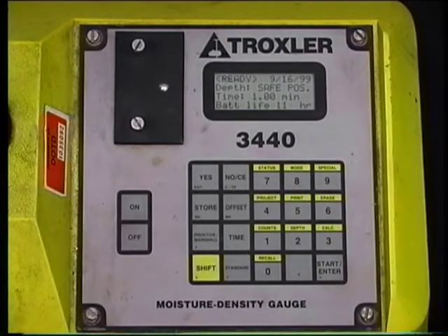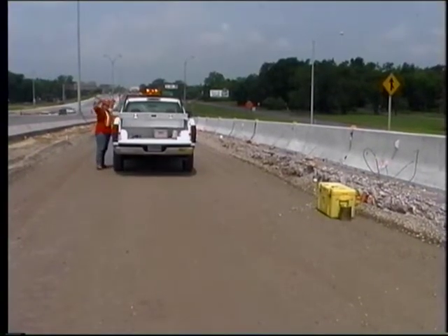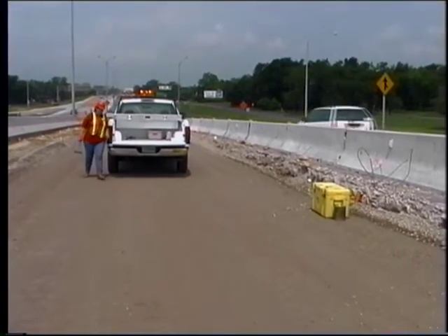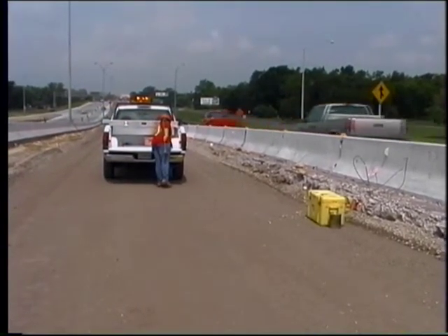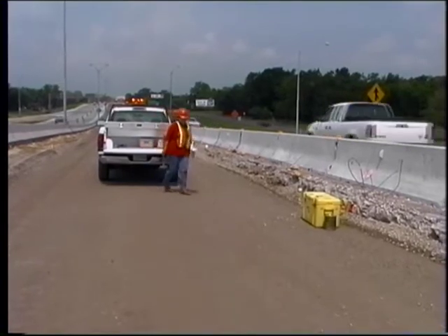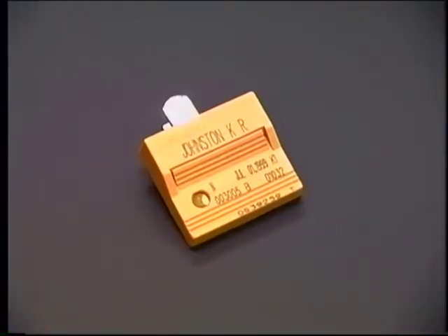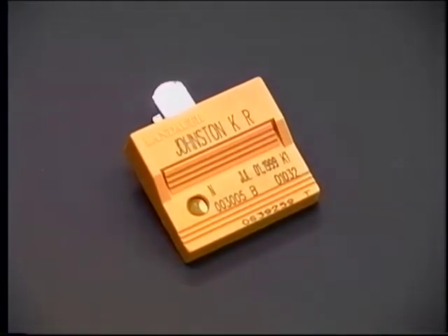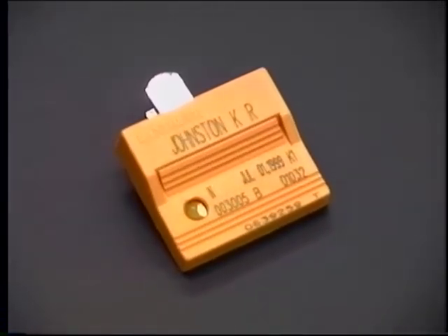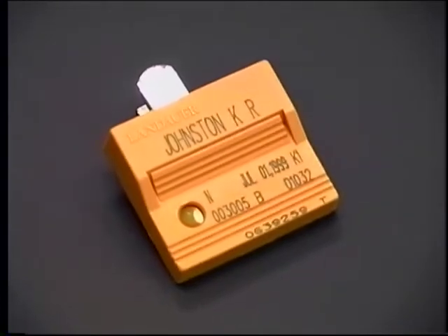If you use this equipment as instructed in your training manuals and the operator's manual, there is no danger of overexposure to radiation. However, improper handling, transport, or operation may lead to radiation hazards. The TLD badge, which registers exposure to radiation, is to be worn at all times when transporting, handling, or operating a nuclear device.